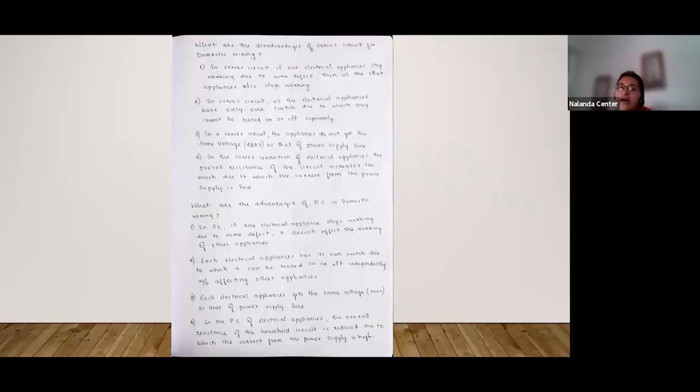Now, which one is preferable in domestic wiring? Is series preferable or is parallel preferable? See, in series connection, the effective resistance is going to be more, so it is not preferred. Consider that your fan, heater, AC, and washing machine are in series. If you switch on one switch, your fan, washing machine, AC, and everything is going to go on. It is not advisable. They cannot be controlled by individual switches. So you're not going to use series connection, except in two cases that we are going to discuss.